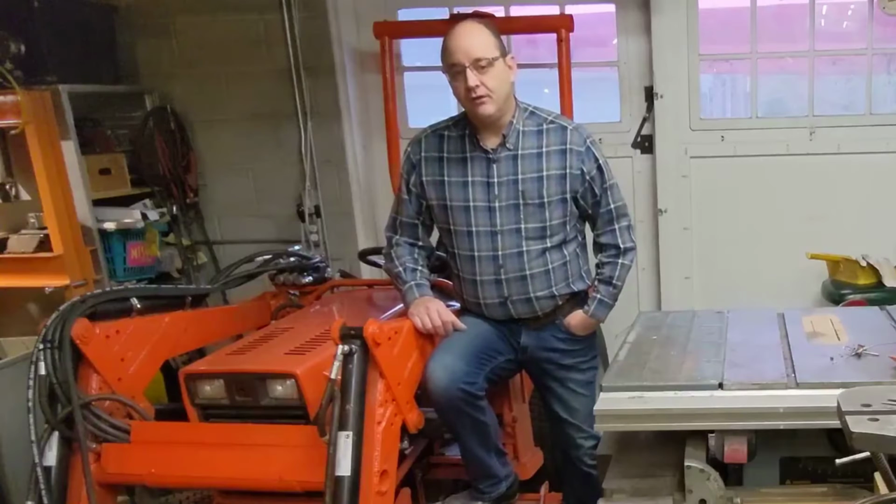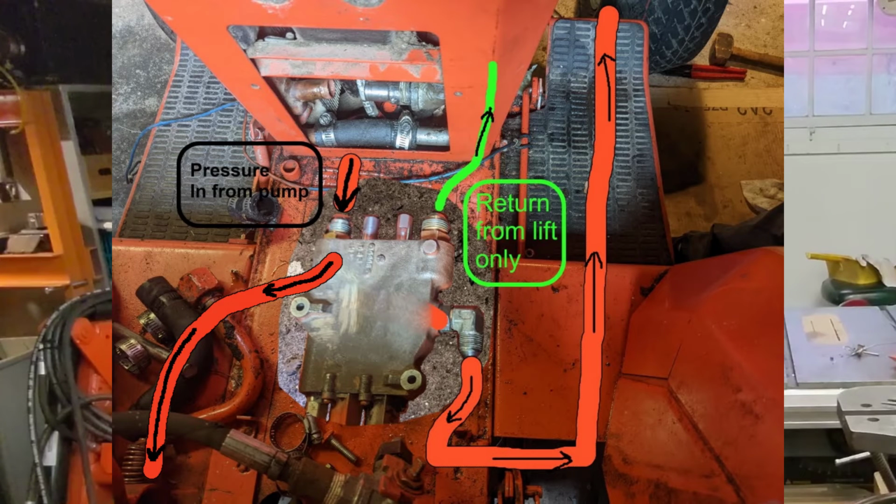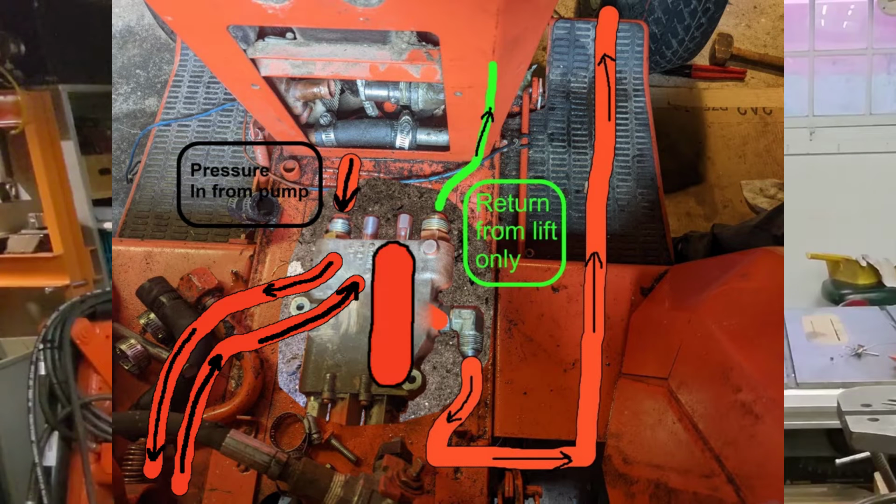If you activate the travel spool, the high pressure oil will head from the travel control valve through the travel motor and back, causing the tractor to move. After passing through the motor, that same oil will make its way into the lift circuit gallery, where it's available for use by the lift cylinder if needed. From that gallery, the oil is directed out the power beyond port.